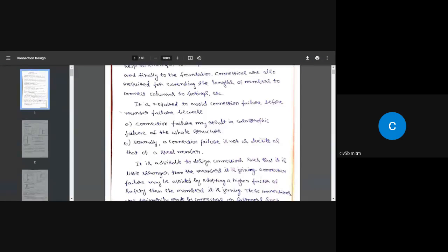First we put the reinforcement, and bend it as per the requirement. Then put concrete, and once the concrete is set, cure it and take the scaffolding or supports out after certain days, 21 or 28 days. Then the structure is going to act monolithically as a single unit.